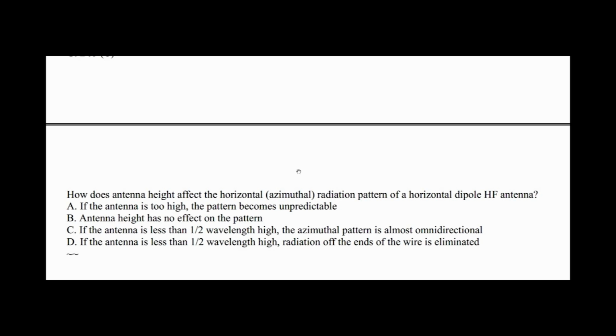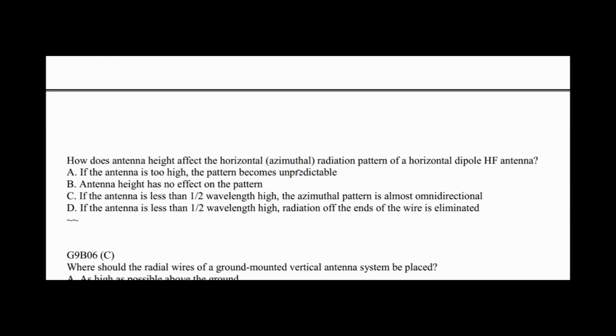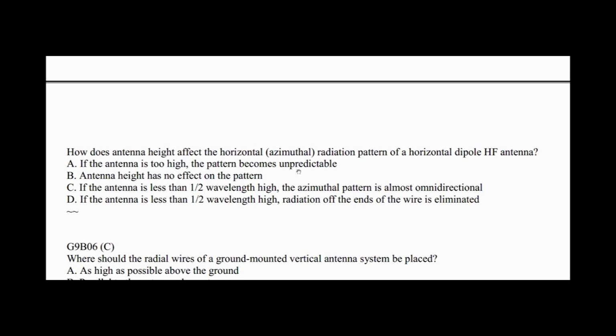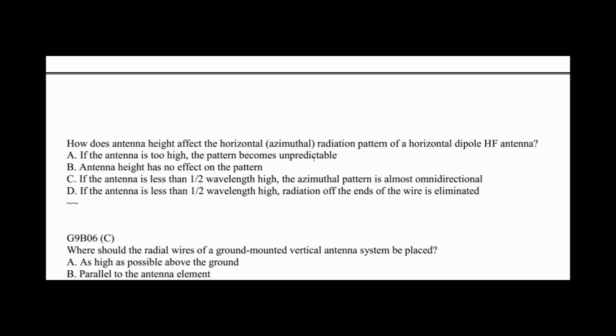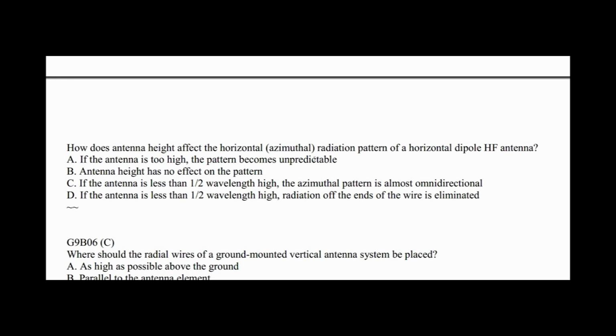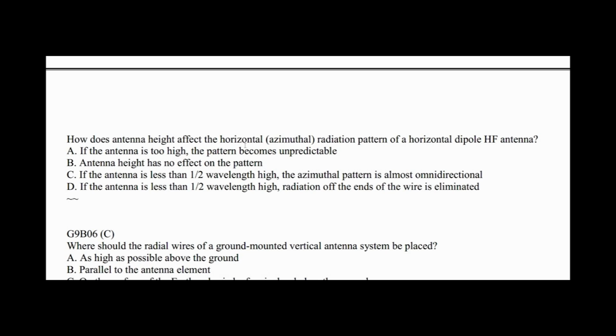That's their answer. I strongly disagree with that. It depends, and it depends on a lot of things. It depends on the topography, for one thing. So if that dipole is half a wavelength high, its effective height for me on the side of a mountain is very different, and it's not omnidirectional. That answer needs to indicate flat ground and a bunch of other things.